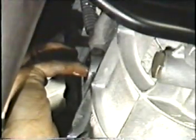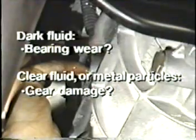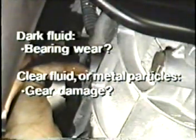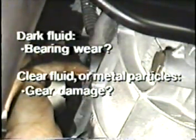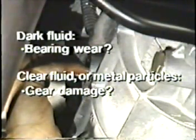After your test drive, be sure to check the transmission fluid. Dark or dirty fluid may indicate bearing wear. If the fluid is clear, check for fine metal particles sticking to the magnet on the drain plug, which could be a sign of gear damage.